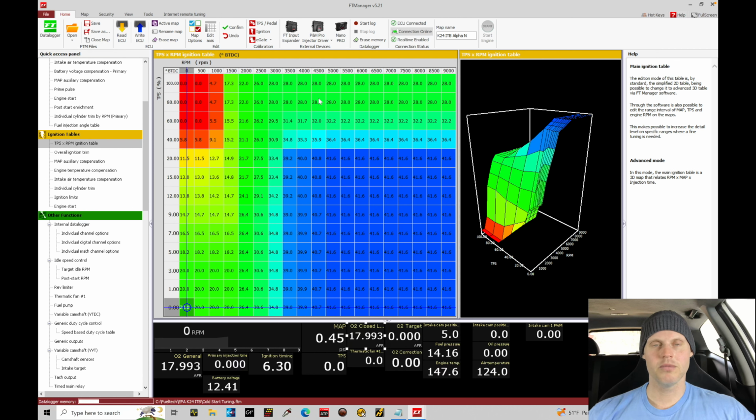That's definitely relatively high for what I'd expect for this compression ratio for petrol fuel, but we always have to keep an open mind as we're calibrating and tuning our spark timing. Every engine's going to be a little bit different in what it's going to respond to. This is going to be a good starting point, and usually when we engage VTEC, we might be able to bump the timing in just a little bit higher than when we engaged our low cam or non-VTEC spark timing.